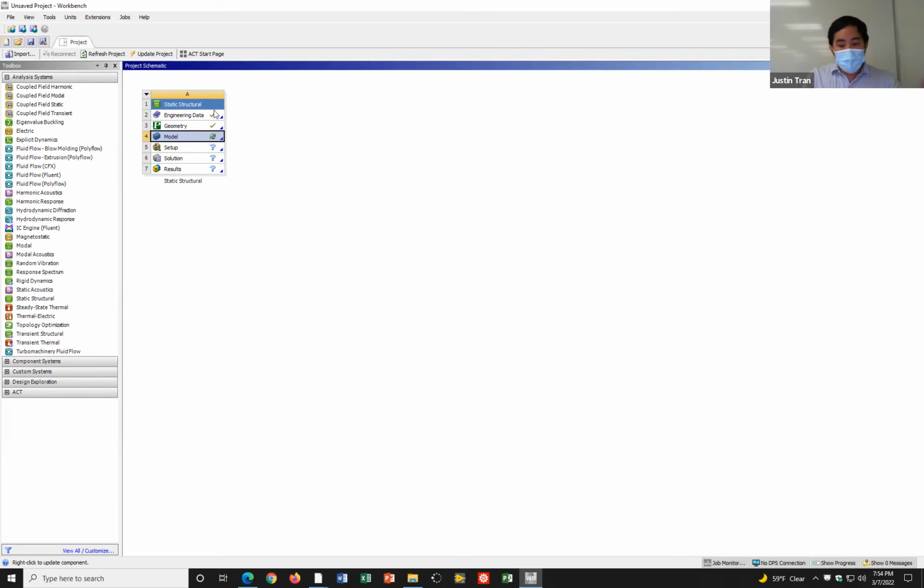And kind of generally speaking, as you go about using Ansys, if you have a green check mark, that means you're usually good. Okay, so that means that Ansys has all the data that it needs from that part, and you are ready to go on to the next step. Okay. All right, and so the next step will involve launching Ansys Mechanical. Ansys Mechanical is our program where we're actually going to apply our mesh and boundary conditions and run. And so to open up Ansys Mechanical, you can double click on model right here.